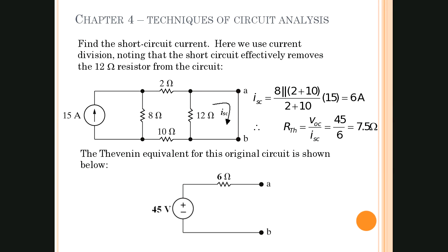So now, if we remove this, and I'll do this in red, if we remove this, and we're left with this component and this component, realize that now these two components are in series together. And so we have 2 resistors in series, which is 10 and 2. We can go ahead and add those up together, and that gives me 12 ohms.